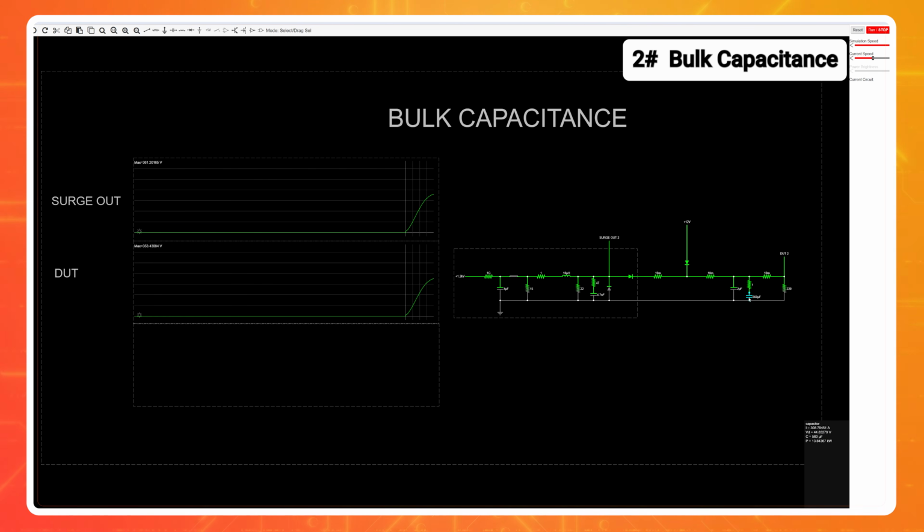It's such a short event. They could be okay, but you're never really going to want to rely exclusively on an electrolytic for a surge event. It can work really well as a layered protection, but on its own, you're probably going to damage that cap and still almost certainly damage your circuit.